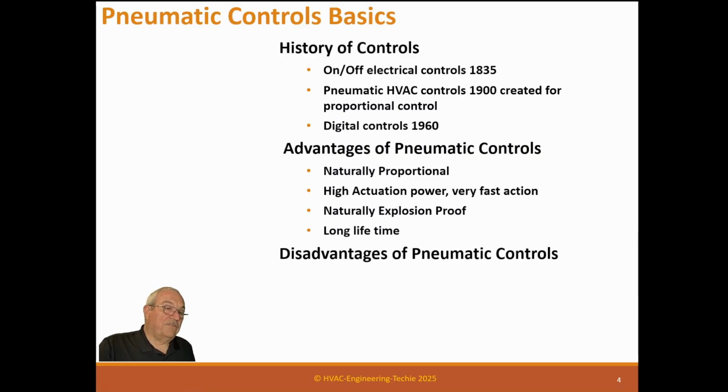However, they have disadvantages. They require clean, dry air. If you pump water into them, I'm sorry, sir, you just ruined your system. Now, in the old days, back when Powers was making pneumatic controls, by old days I mean 1965, 66, you could put water in them and it would just drain out and you could keep on going. But modern pneumatic controls, by modern I mean from 1975 on, if you put water in them, you bend the Bourdon tubes and it's now totally out of calibration. Sometimes it's so bad you can't calibrate it, and they have to replace the device.